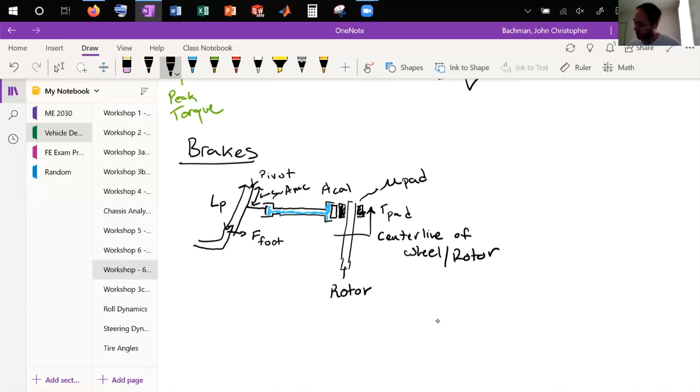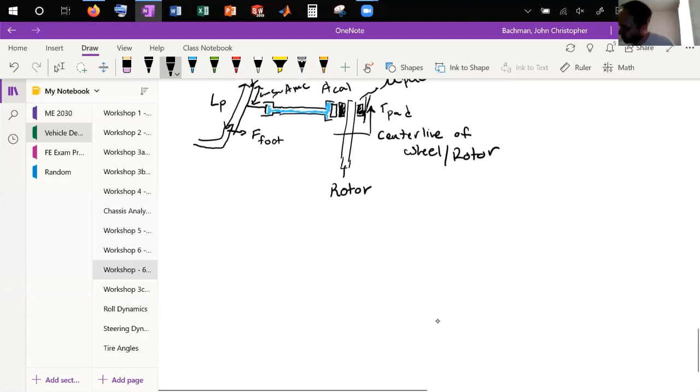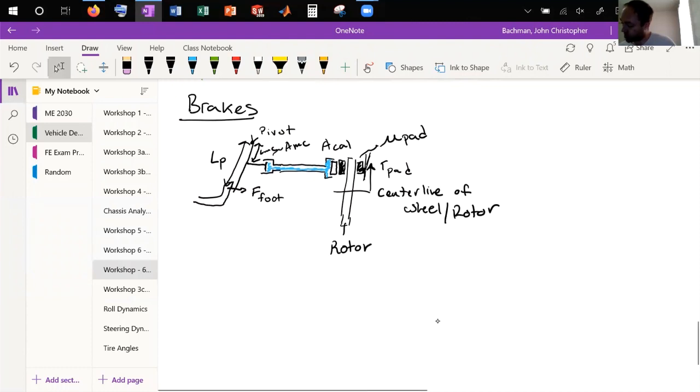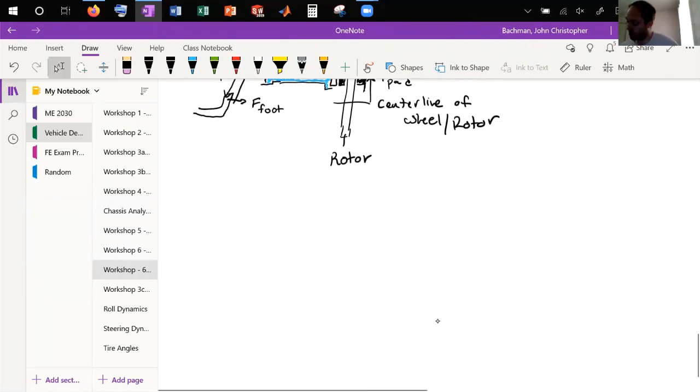This is a simplified schematic of pushing this whole thing together, basically. This is kind of fixed on the other side of the piston. Putting a piston on the other side helps make it more symmetric, and also helps bring the pads off of the disc so it's not rubbing at all times.